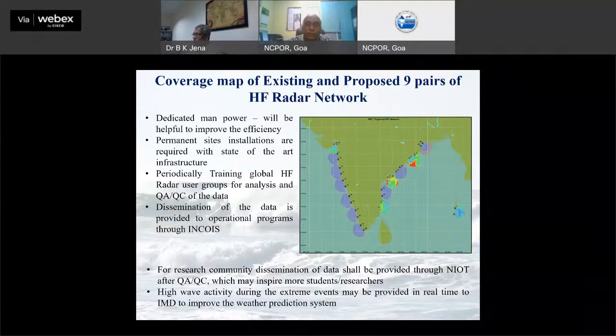But I would like to inform him that ADCP cannot measure the 2.5 meter surface current. We have compared ADCP data, which is 5 to 10 meters below the surface, and it is matching the trend. And we have put a surface drifter, and when you take the drifter plus HF radar trajectory, it is matching very well.